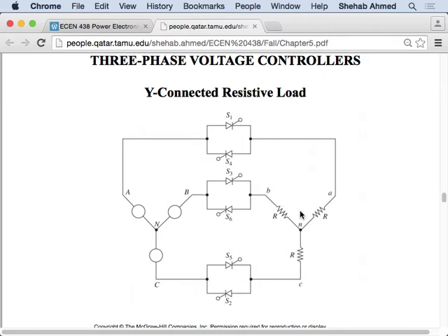In this case, what's going to happen? We will have current in the neutral wire if we have this neutral wire connected, right? What is this current, and what is it an indication of? It's an indication of some imbalance happening in the system. Imbalance in the system is something that we will deal with mathematically in 459. Here, we will not allow it to happen. From a control perspective, we will assume that our voltage sources are balanced and our loads are balanced.